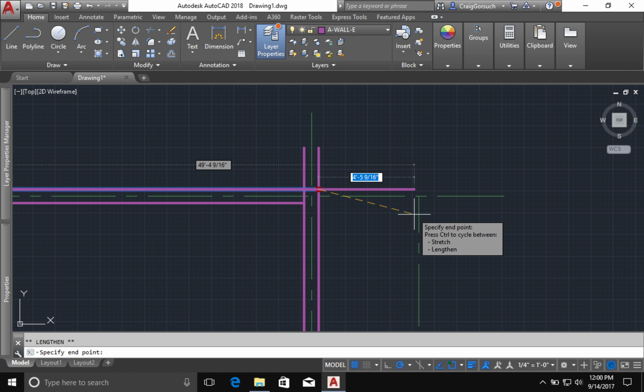come down. Now you notice as my mouse moves over this vertical line, it says endpoint. I have that square that shows up there. In order to select the endpoint, I do not need to move my mouse where that green square is. As long as the green square is showing up, when I left click, AutoCAD will accept the endpoint as the actual coordinate that I want. So left click,